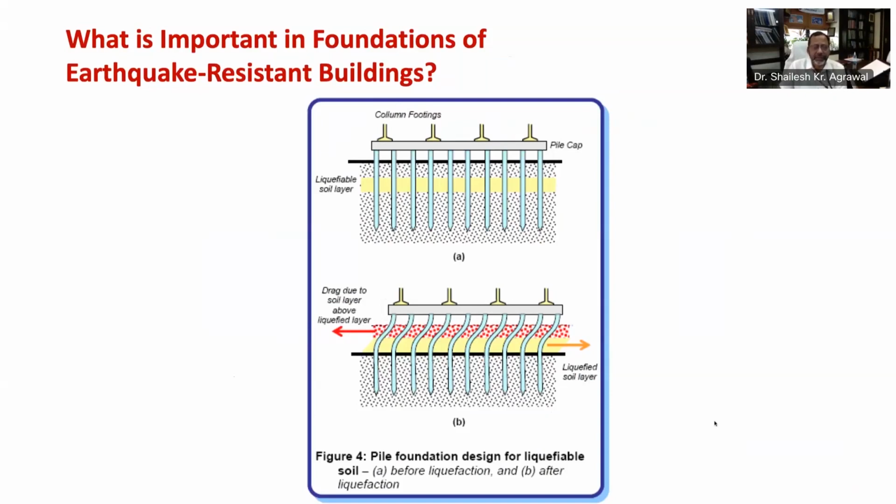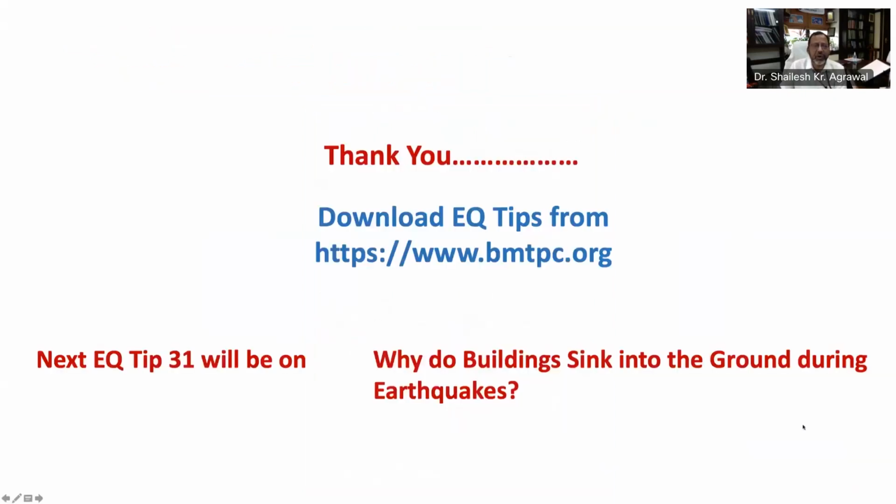That means the foundation system needs to be designed for loads higher than ultimate flexure capacity of columns or of structure walls. This is all about earthquake tip number 30.